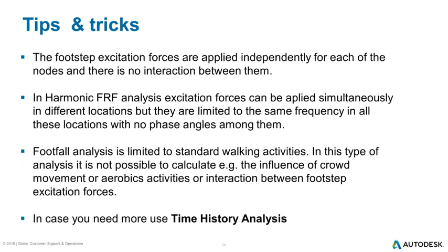Mind that the footstep excitation forces are applied independently on each of the nodes, and there is no interaction between them, even when full excitation is activated. This is how the code requires this analysis to be performed. In case you have different types of excitations than a typical walking, you should use the time history analysis instead.